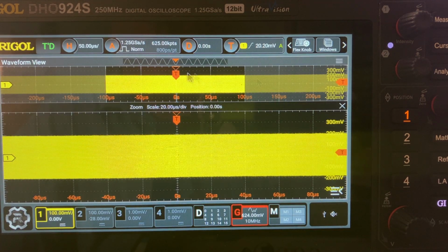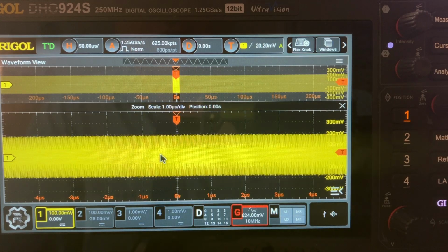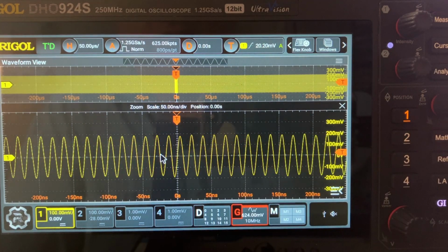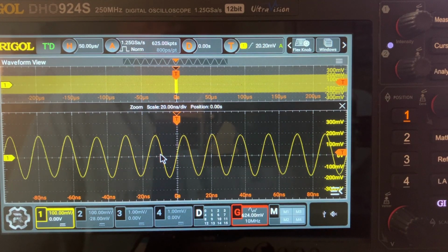So the entire memory, 50 micros. Well, you could reduce the number of samples. It won't change the frequency that is displayed, but if you zoom on it, you will end up at the same place. And you see, well, it's there. It's 60 megahertz, but it's dancing a lot, and it's not very clean.